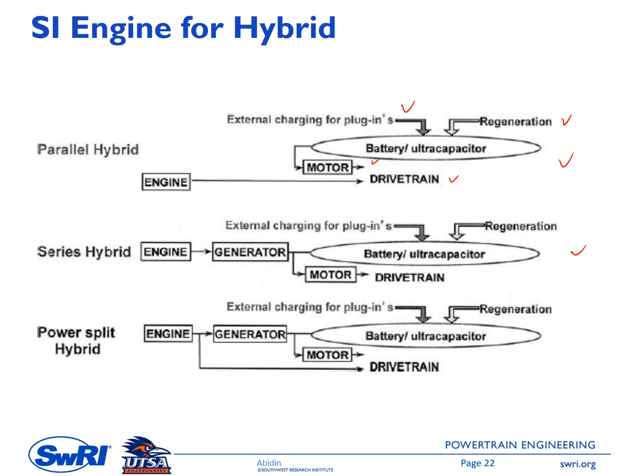Okay, parallel hybrid. The second configuration is called a series hybrid. In this case, the engine is not connected to the drivetrain; rather it is connected to the generator to generate electricity that can be used to propel the motor, and the motor will drive the wheel of the car. The battery can also be charged from regeneration or from the plug-in.